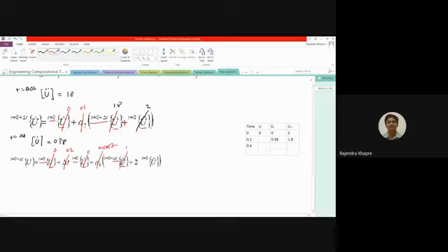So this value I am going to substitute as 1.8, and this is the acceleration at t is equal to 0. So acceleration at t is equal to 0 is 2. So this value is basically 2. If you solve this, you are going to get the displacement at delta t. This value is coming out to be something like 0.0386. Okay, so here I am now going to write down 0.0386. In this way you have to get the response of the structure for the first step.